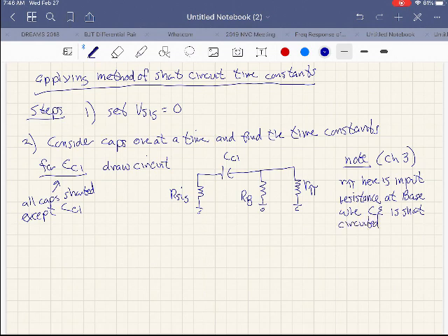Okay, so you just have series parallel stuff going on right here. We can say CC1 sees resistance. Let's write it out here. We'll call it RC1. We've got RB, that's that parallel combination of RB1 and RB2 in our original circuit, in parallel with R pi.